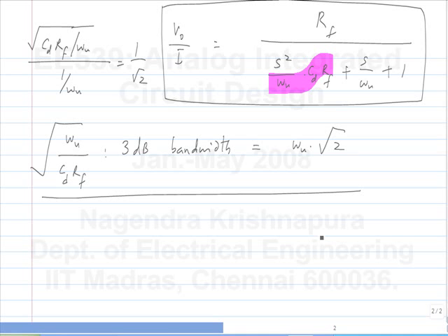So, first of all, there are several ways of doing this, and I think some of you have done it that way also. You just started with some RF and then kept on adjusting it until you get no peaking. That is fine, but I think after going through a class like this, you should also know the theory so that you can calculate right away what the value of RF is.